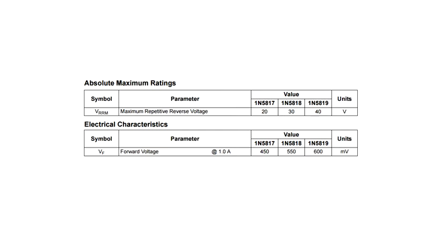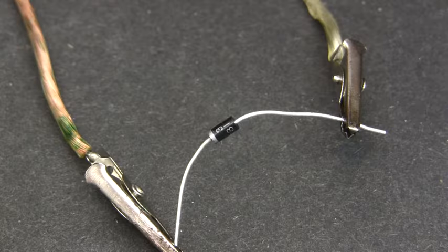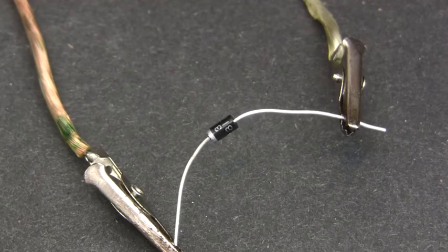Now there's one last thing I want you to know about diodes, and not many people realize this. The forward voltage drop tends to correlate with a maximum voltage rating on the diode. When searching for diodes, you might be tempted to go out and buy the diode with the highest voltage rating possible, because then you'd have a larger safety margin. Well, you can do that, but you'd be sacrificing efficiency. Try to figure out what your peak reverse voltage is, and pick a diode that's rated for about 10 volts more than that. But make sure you figure it out accurately, otherwise...